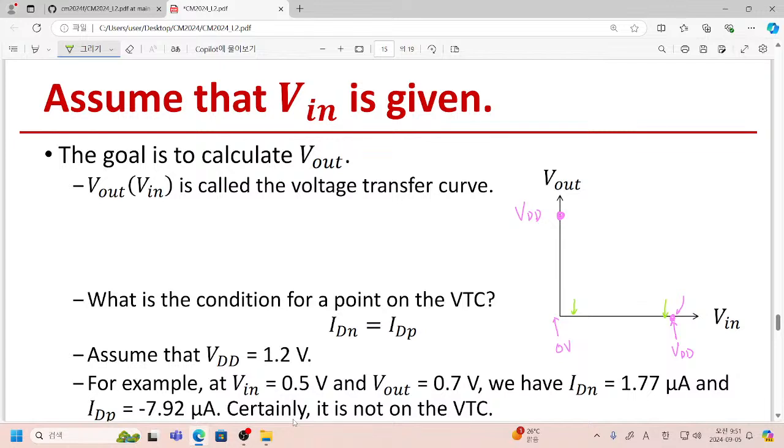So now think about some artificial system like this. Just assume that you have such a relation between your input voltage and output voltage. Then certainly when you have exactly 0 or exactly VDD, your system will act as an inverter, a logical NOT gate. However, this green line shows a system which is extremely weak to external noise.